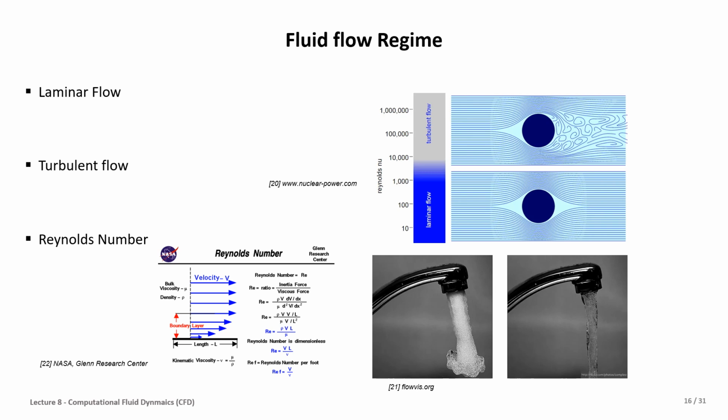And for laminar flow, we are able to find the analytical solution. But when we are dealing with turbulent flow, as we can see, when flow is passing the object, this cylinder, there is a wake and complex geometry for the flow in the downstream. This complexity could be seen in the solution, and it makes dealing with the analytical solution for this kind of problem difficult.